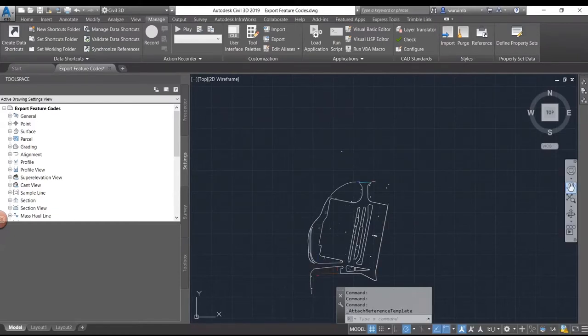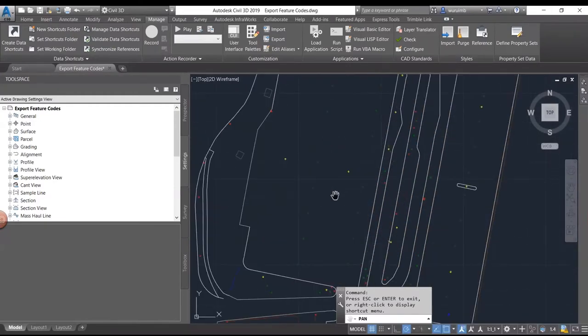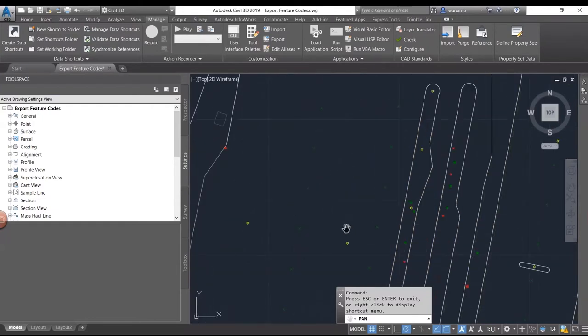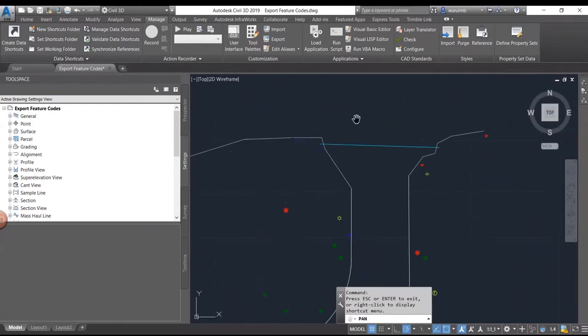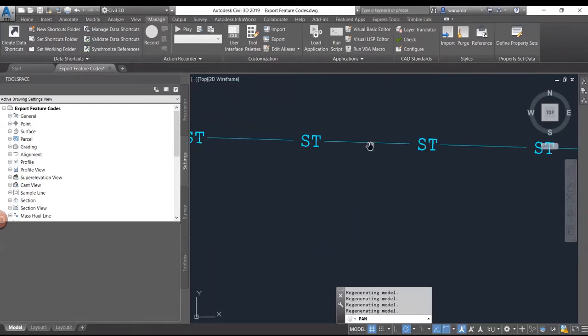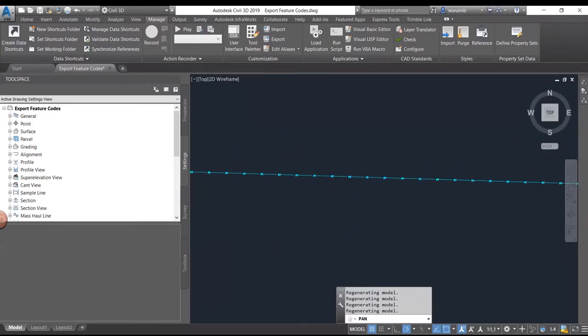There we go. So basically by doing this reference style, Civil 3D will utilize existing layer definitions from our template DWG file and then recolor and redesign or display all of these line styles. So if I zoom into this line a little bit and come all the way back, now you can see this line style has been carried over.